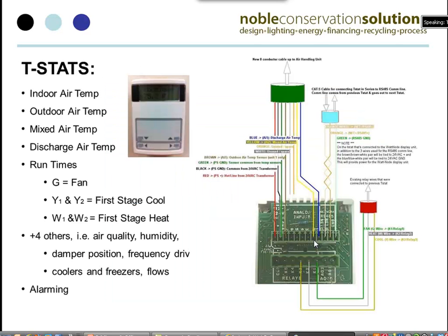We use programmable controllers as thermostats that help us collect this information, taking what's read off the sensors connected to these thermostats, both indoor and outdoor air temperature and a number of other things, and feeding that into the InduSoft system so they can see it in real time as well as in the database for certain analysis and different types of trending.